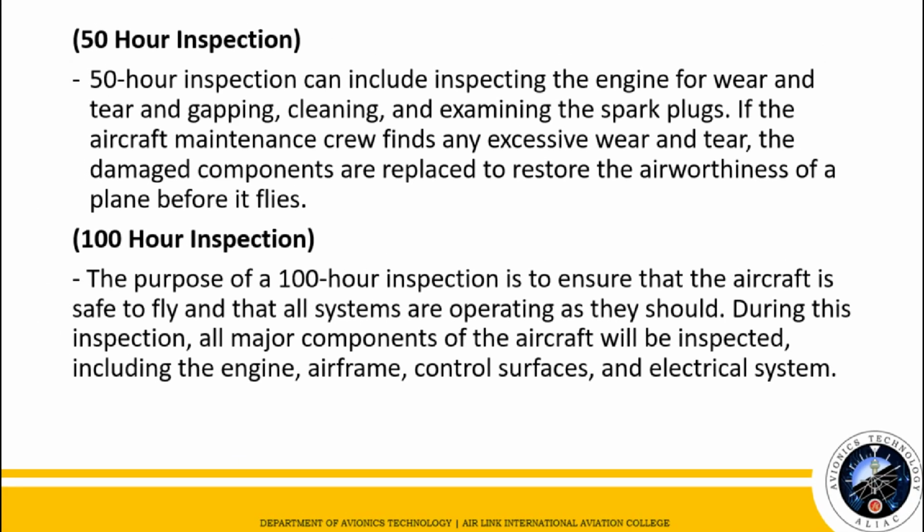50-hour inspection. The 50-hour inspection can include inspecting the engine for wear and tear and gapping, cleaning and examining the spark plugs. If the aircraft maintenance crew finds any excessive wear and tear, the damaged components are replaced to restore the airworthiness of a plane before it flies.